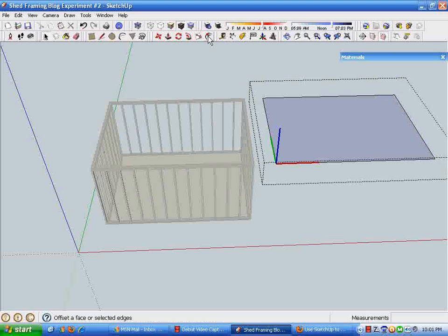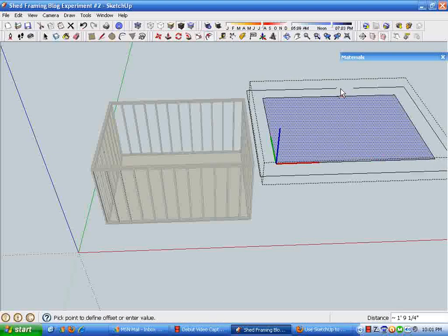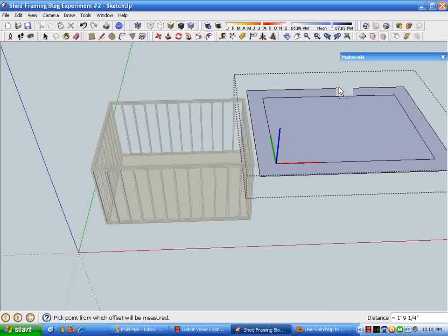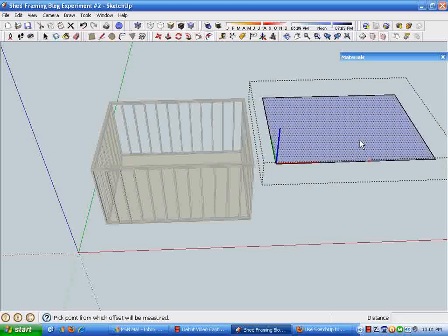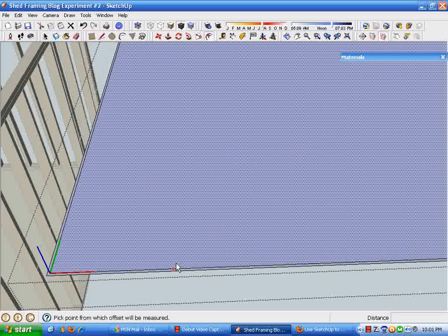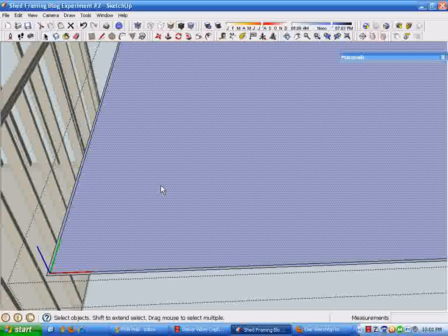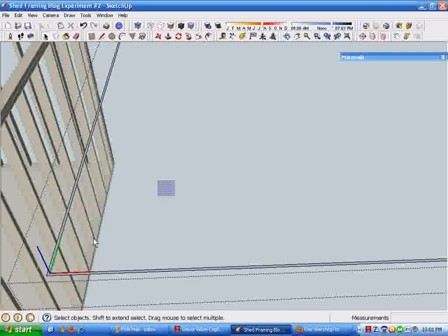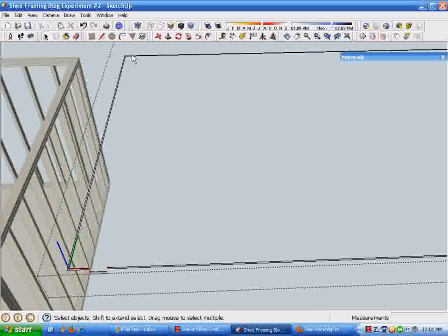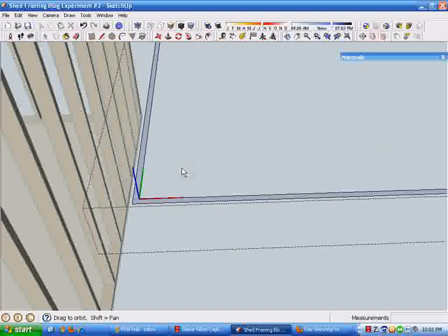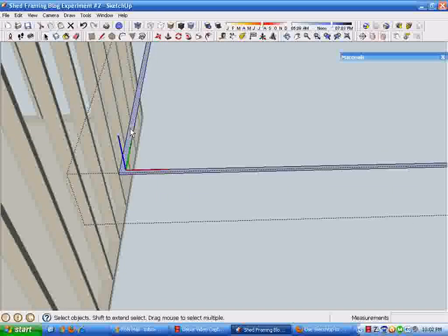I'm going to choose the offset tool to get this job done, and what I've done is click with the mouse and drag to the outside of our rectangle, and I'm going to tell SketchUp I want that line to be ½ inch bigger than the rectangle we started off with. And by deleting the face, now I have a little strip of what's turned into plywood. Reverse these faces, and this little strip, now the interior perimeter of this, the exterior perimeter of our wall plates,